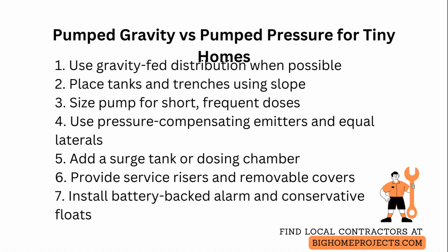Include a surge tank or dosing chamber between the septic tank and pump to decouple pump cycles from household water use so that dosing volumes remain consistent and solids do not reach the pump. Always design access points and service risers so the homeowner can inspect and pump the tank without heavy machinery, and specify removable covers over distribution boxes for easy balancing and cleaning.